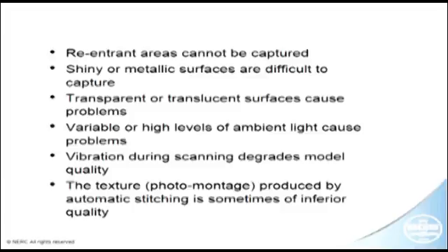We also found that if you do it in a lab with sunlight shining in, that can cause problems. The best results we've actually seen was one of our project partners who had a dark area with a wall-mounted slate slab, and the scanner, when it's placed on that, it cut out the light, it cut out the vibrations, and it gave very, very good results indeed.